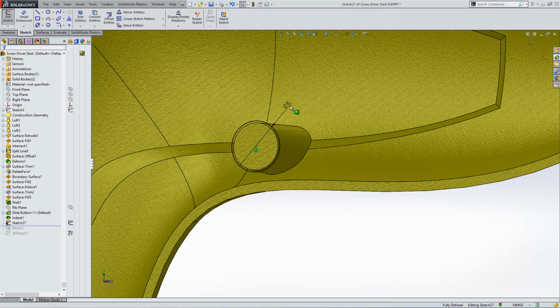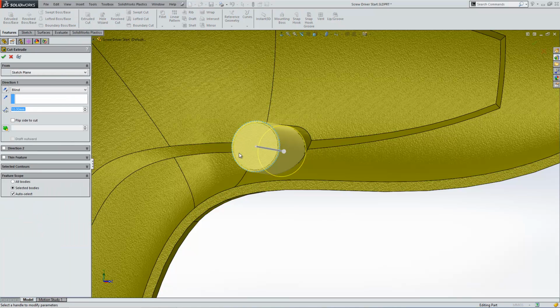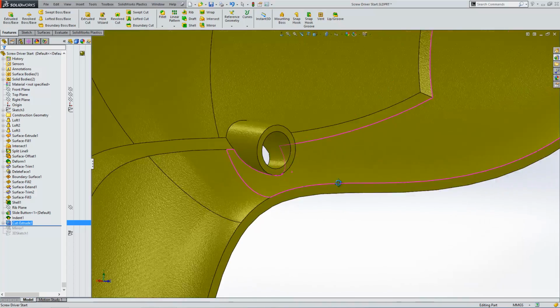Okay, with this item dimensioned at the right size, I'm then going to cut this straight down into my model, and I'll choose the extrude cut tool and just cut down by 6.5. There we go, and that gives us that shape cut into the model.